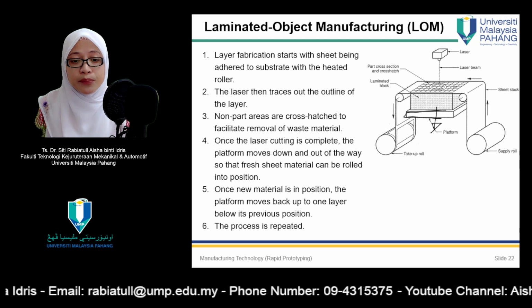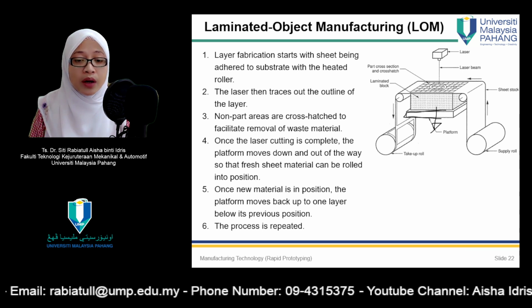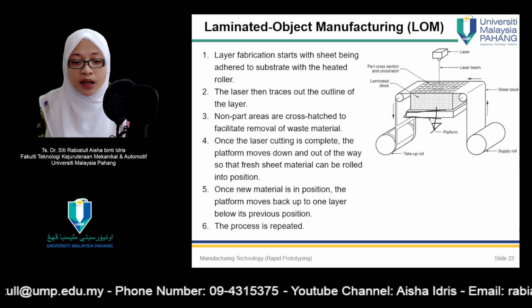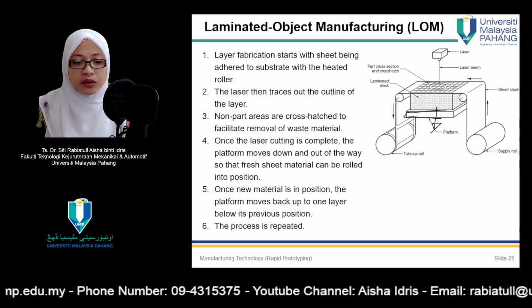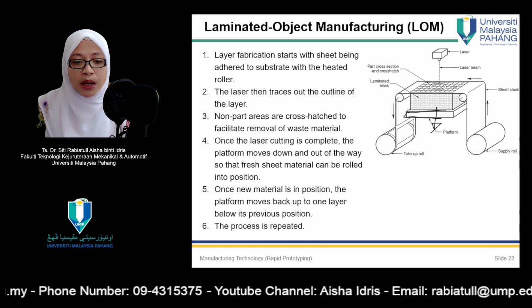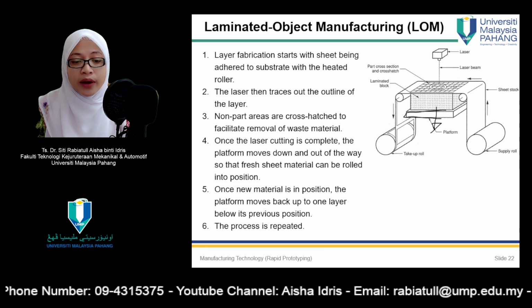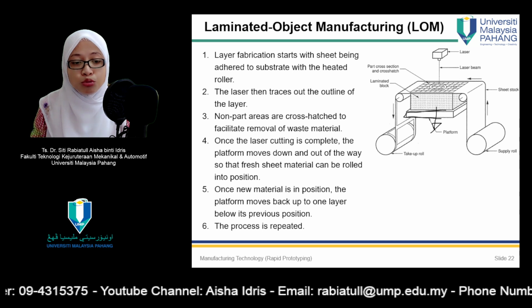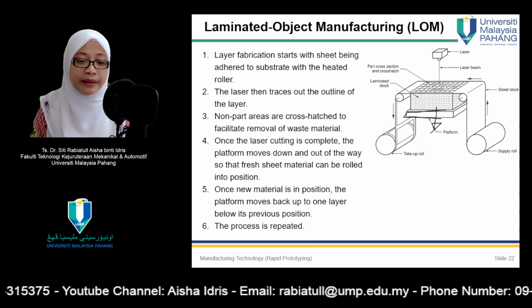The laser is typically a 25 or 50 watt CO2 laser. The cutting trajectory is controlled by means of an XY positioning system. The cutting depth is controlled so that only the top layer is cut.